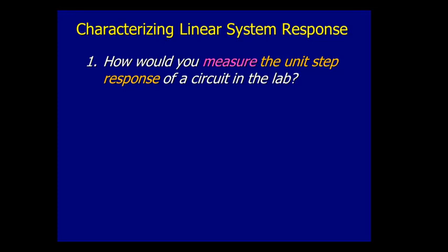All right. Anything I want to do special to the parameters of this square wave to make it really good for a step response? Lower the frequency. I want low frequency. What's that going to do to my waveform? Spread it way out. Use a really low frequency. How else might I extend it even more?